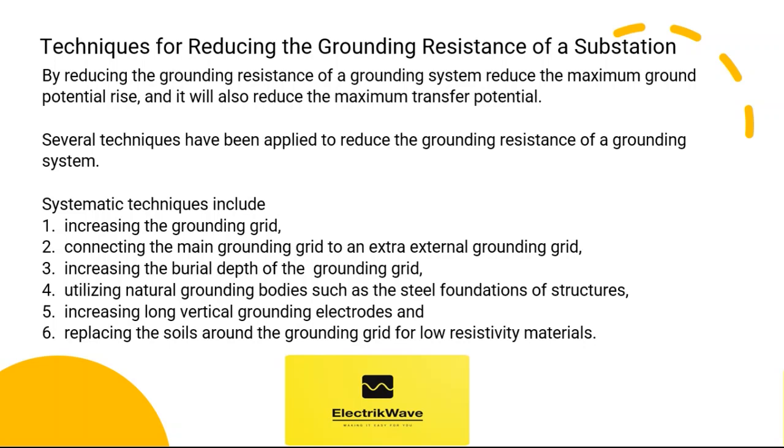In order to reduce the grounding resistance, a unique method was proposed for decreasing the grounding resistance of grounding grids in a high resistivity area, called the explosive grounding technique. This method has been proven very effective, and the only deficiency of the explosive grounding technique is the high engineering cost. We will discuss simple methods for reducing grounding resistance one by one.